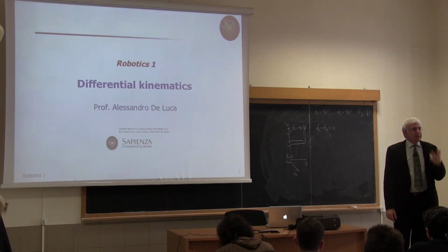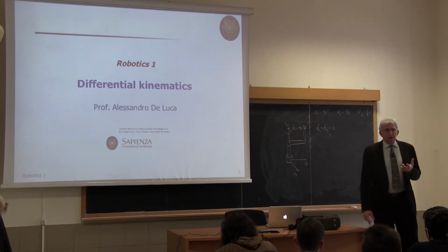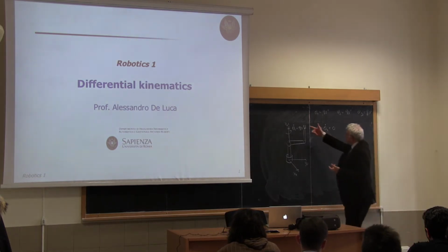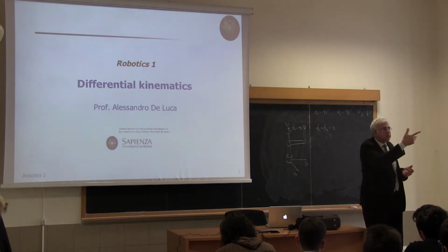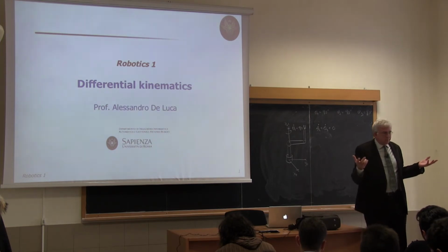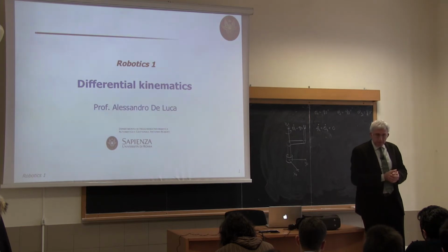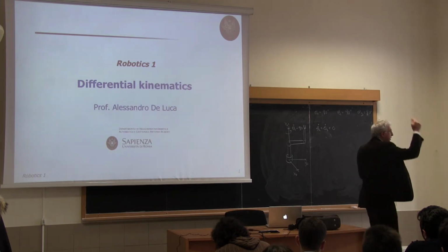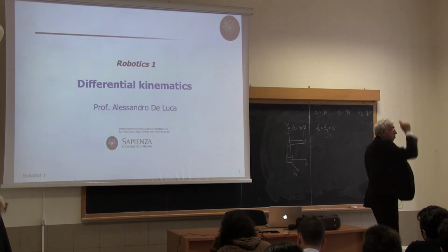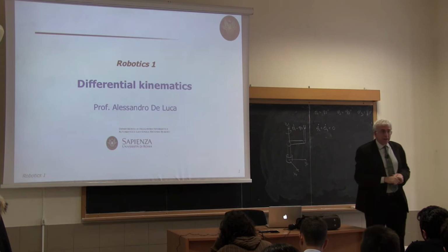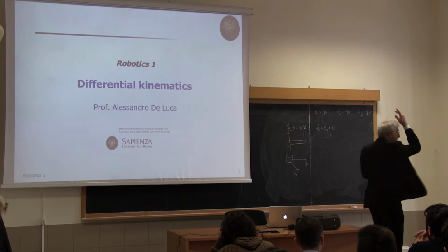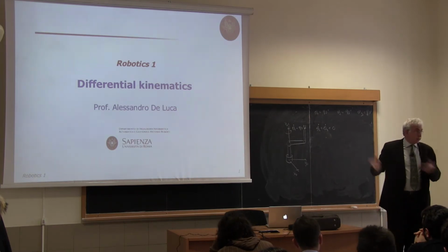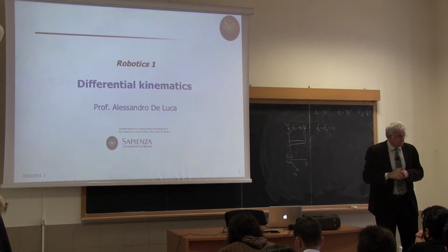How can I state that there is some angular velocity? Well, I just put a frame at the end effector, and if this frame is changing orientation, then it's clear that there should be an angular velocity for that. In the same way, in the example with the end effector on top of the joint axis 1, the origin of the frame was exactly there, so when I'm rotating joint 1, the origin is not moving. This is why the velocity is 0 in that case.